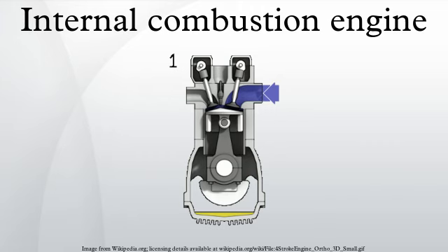Split-cycle engines separate the 4 strokes of intake, compression, combustion and exhaust into 2 separate but paired cylinders. The first cylinder is used for intake and compression. The compressed air is then transferred through a crossover passage from the compression cylinder into the second cylinder, where combustion and exhaust occur. A split-cycle engine is really an air compressor on one side with a combustion chamber on the other. Previous split-cycle engines have had 2 major problems: poor breathing and low thermal efficiency. However, new designs are being introduced that seek to address these problems.